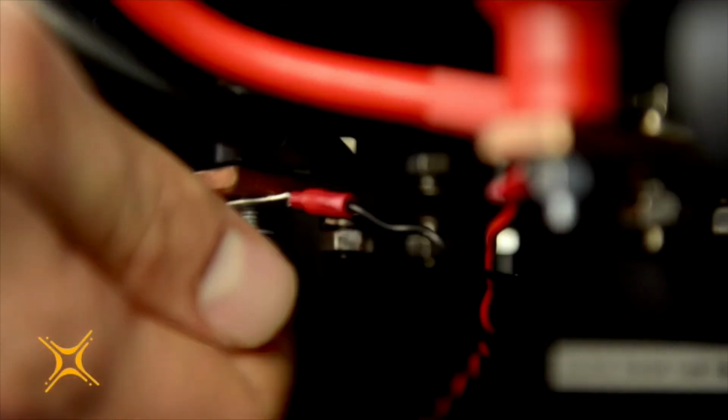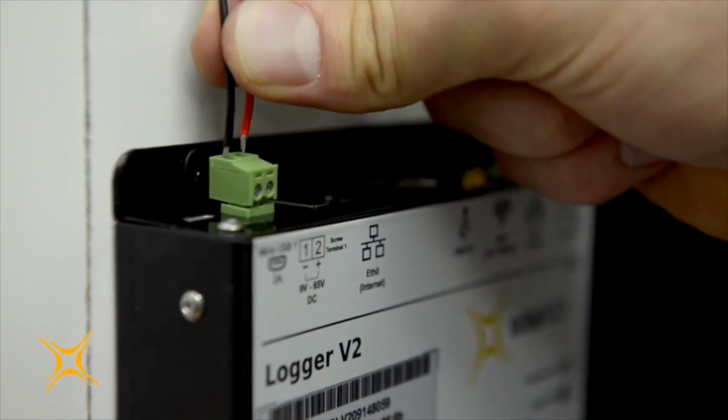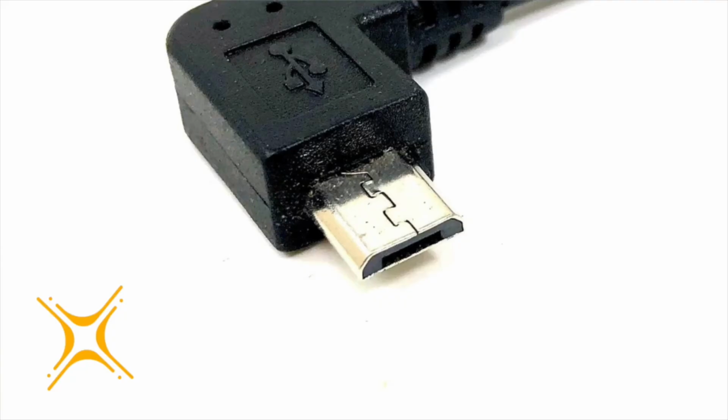Step 4. Powering the logger. Connect the data logger directly to a 9 to 65 volt DC voltage source. Alternatively, you can power the logger with a micro USB power supply.